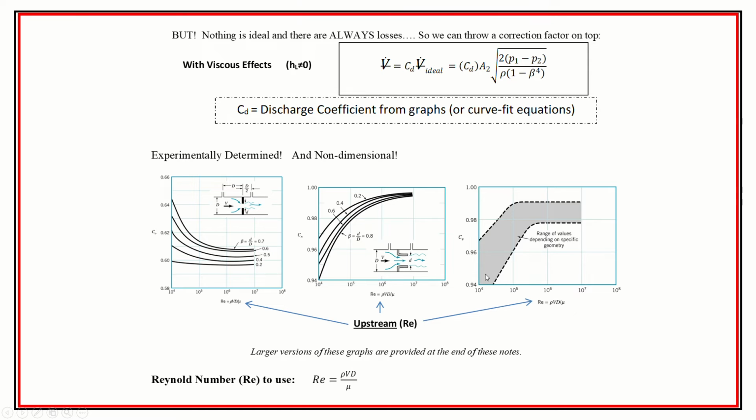And they don't really even give you specific ranges for the Venturi. But you can see just from the ranges that for the Venturi we have like 0.6 to 0.64, in that range right in there. Whereas for the nozzle, it's a lot better because we're sort of in the 0.94 to, maybe, almost to 1. 0.99 it even goes to.